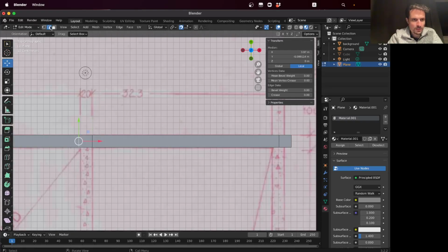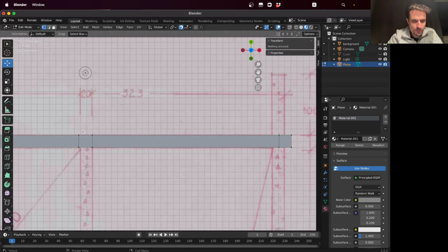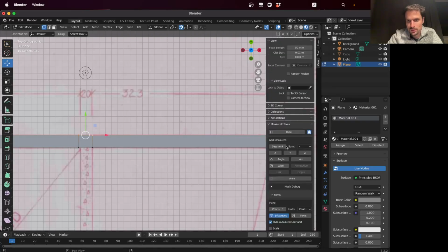So again, if we need to adjust the position, we can in this case create a segment, view segment. We see that it is 22, so what we can do is to select this vertex and move it, pressing holding control like this. So now we can draw this wall. We can extrude this one down and so on.